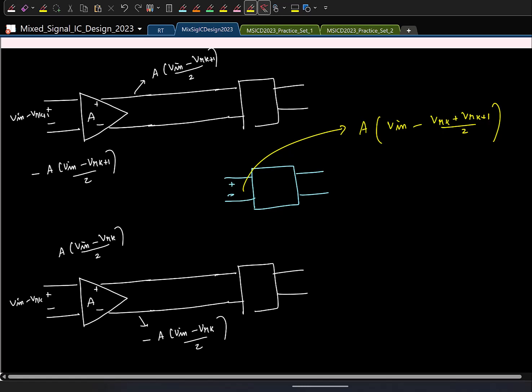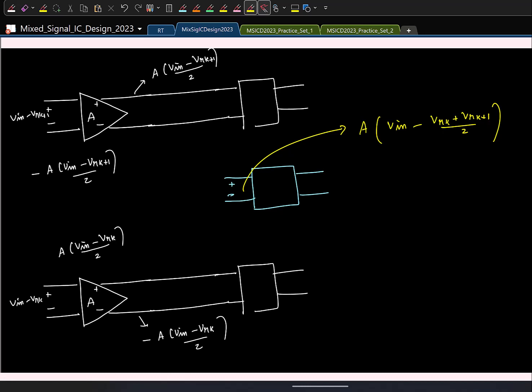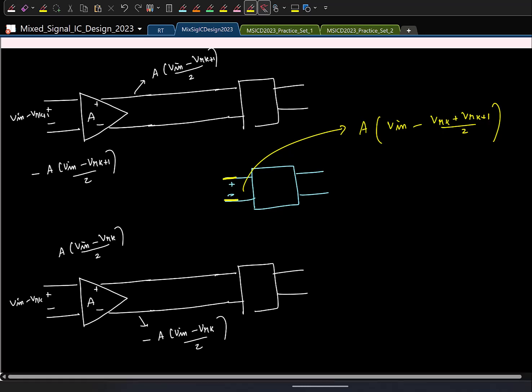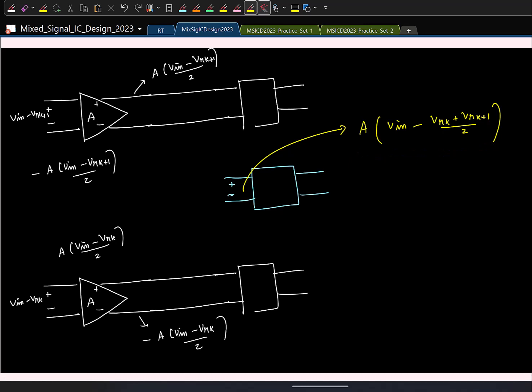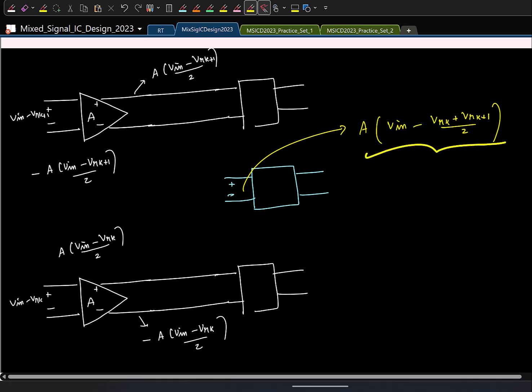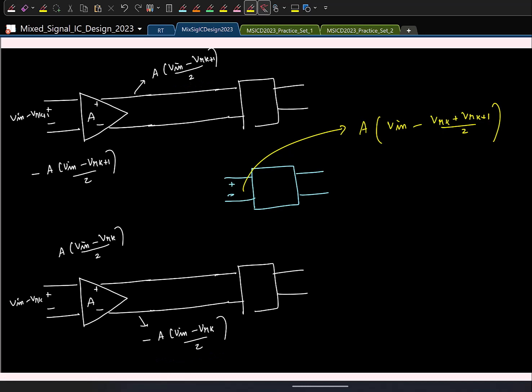Now look at the circuit and tell me what is the simplest thing I can do. What I want is to take the difference between two voltages, and that difference must be this. Look at the circuit. Here you can't put resistors. So what is the simplest thing you can do? I want to take the difference between two voltages, and that should give me this. Are there two voltages in the circuit? One positive and one negative of this. Is that okay? Yeah, then its sign will be reversed, but that's okay.